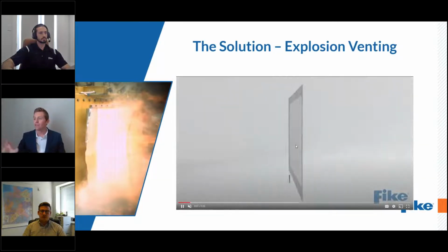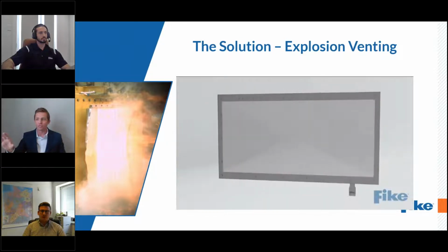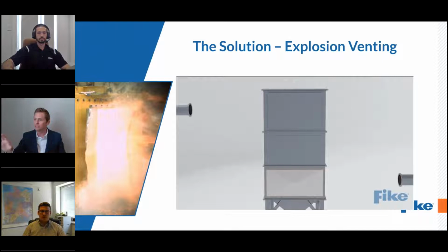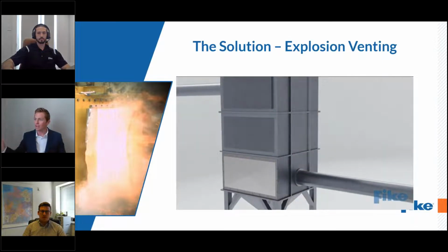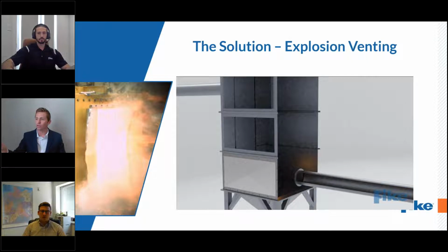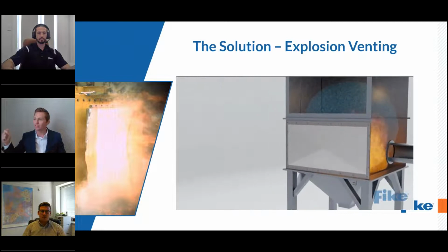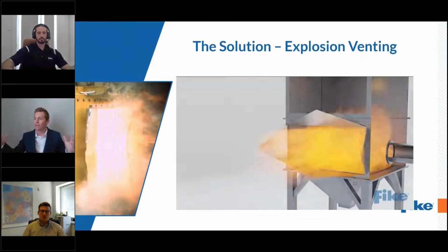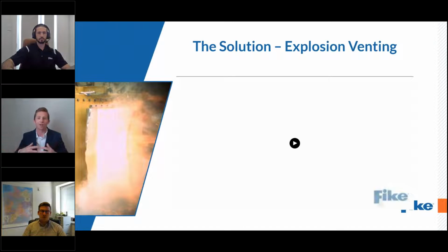Here's a video of the anatomy of an explosion vent. It's really not that complicated, but you bolt it to the side of your enclosure. Here comes the spark on the inlet of the enclosure. It ignites the dust cloud that's in it, because you have air pulse, you have dust layers and things, and it opens in various score patterns, but it opens to a safe area. It doesn't balloon, it doesn't deform the vessel, there's another picture of one. It doesn't create more or less a big bomb to where it could have shrapnel or fireball and injure people. It directs it to a safe area.